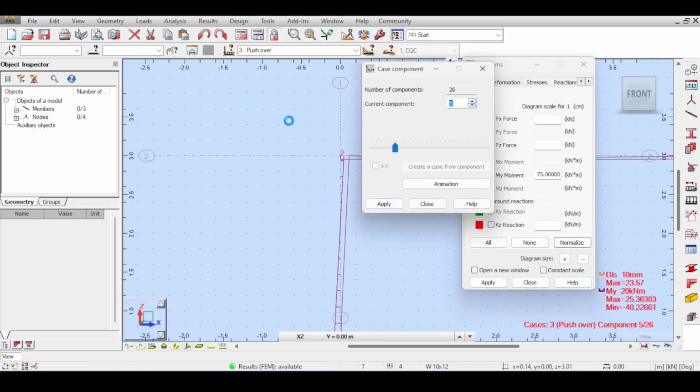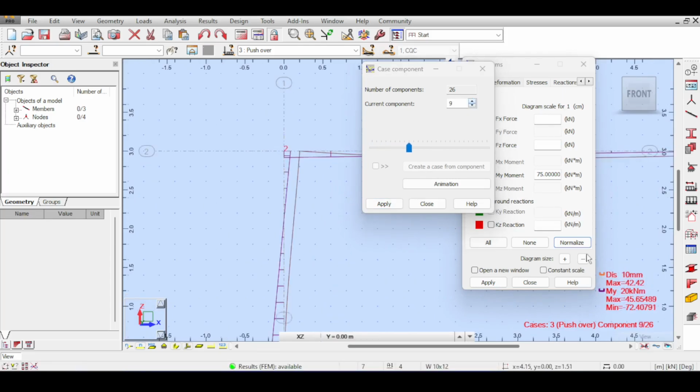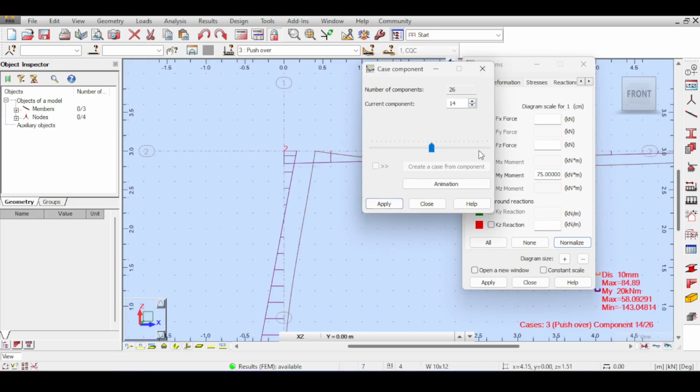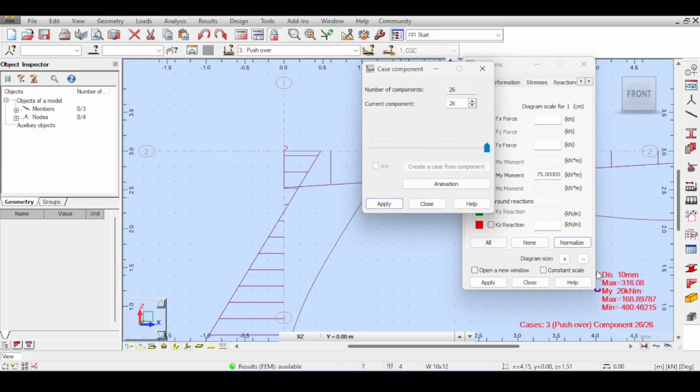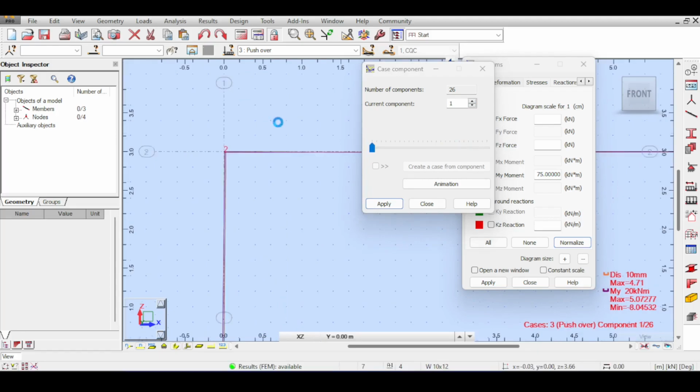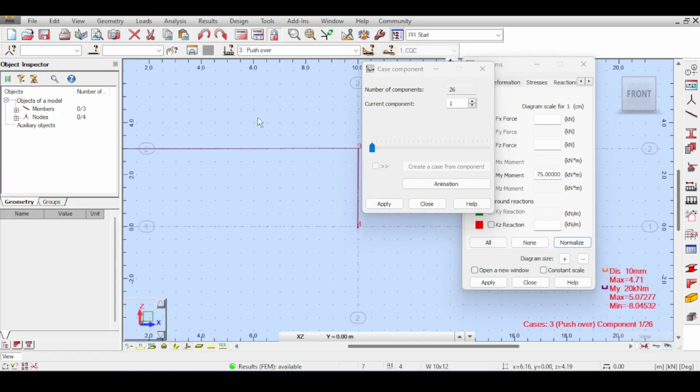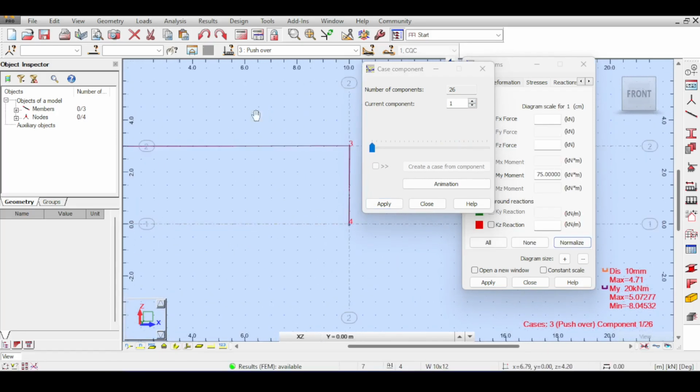You can see that the pushing is happening step by step, and you can see that the displacement increases. And of course, on the last point, the displacement is around 250 millimeters. Of course, it's more because failures happen in the structure, but that's beside the point. So let's take a look at what happens with the structure while we are increasing the pushing over of the structure from the right side.